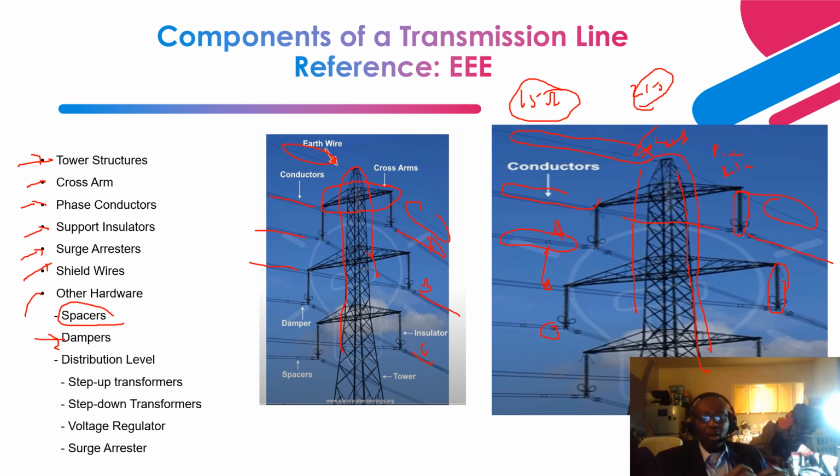During the design of these transmission towers and transmission lines, feasibility studies are conducted based on the worst-case velocity of wind that is going to flow in that area. Dampers are installed on these transmission conductors to damp out the vibration that will occur if any of these phase conductors should be excited by any high velocity wind.